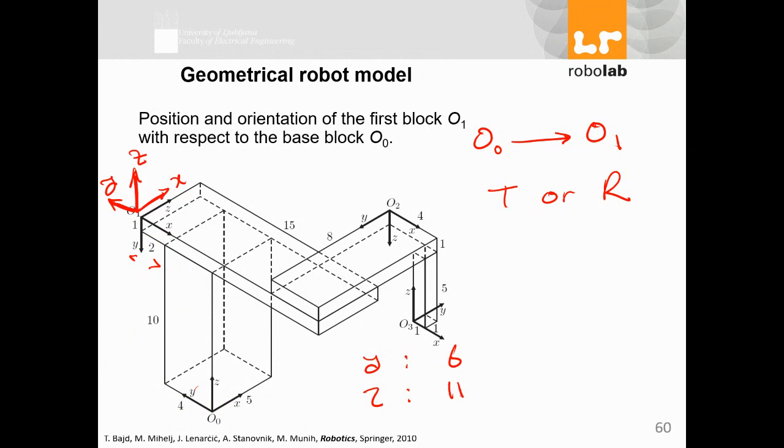Z. So definitely there is a rotation. I agree, 100%. There is at least one rotation. Can you tell me what the rotation is? Rotate Z negative 90 degrees, around Z. Z has become this. You see, this is Z. This is your new Z. If you rotate the translated vectors around Z negative 90 degrees, and then you have another rotation after that, you should get to what you need.